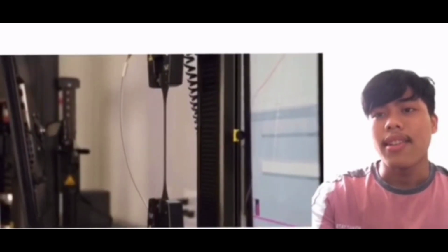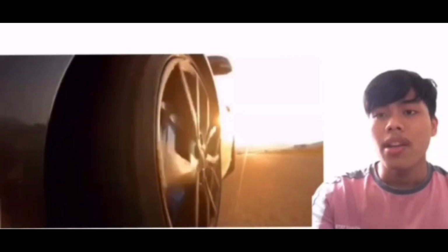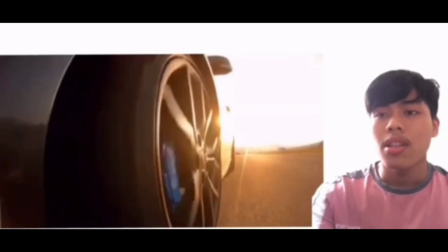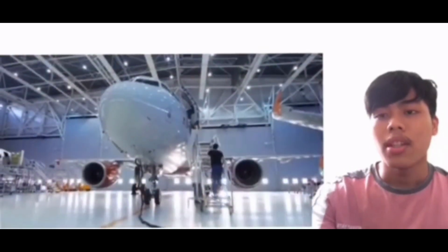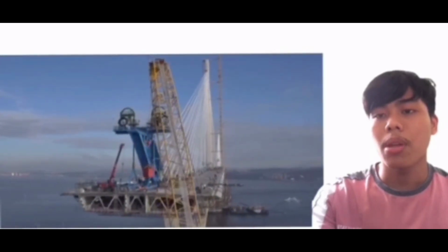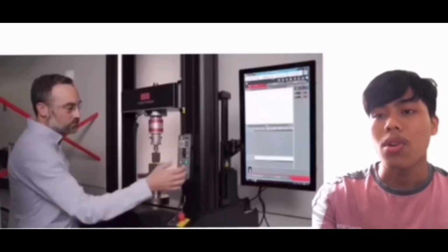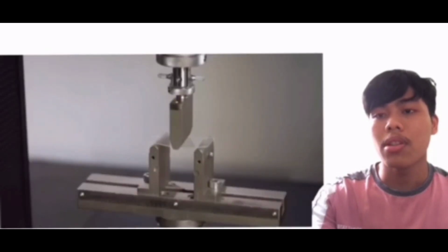Results and analysis. The data obtained was used to calculate stress and strain. Stress equals force divided by area. Strain equals change in length divided by original length. The gauge length for the two specimens was 50 mm, while the average diameter of steel was 9.92 mm and that of nylon was 10.04 mm. The materials were of virtually the same diameter.